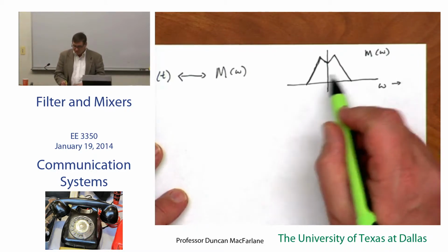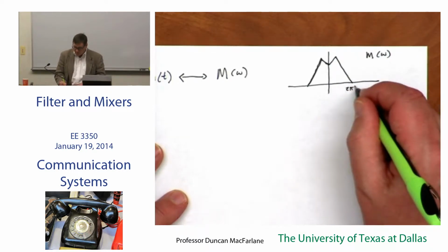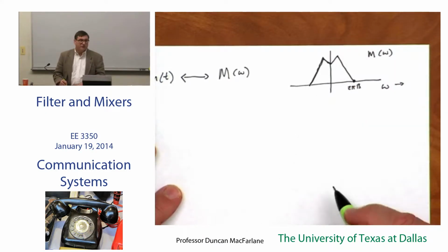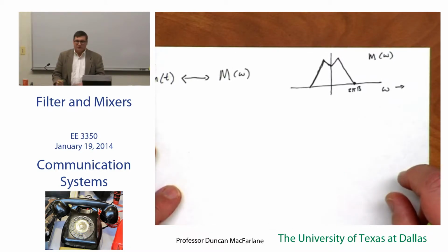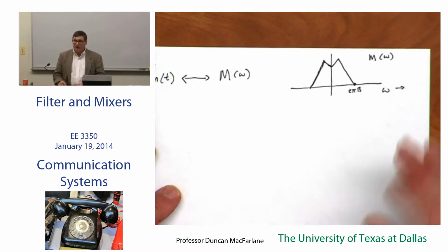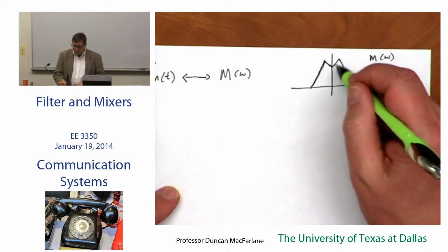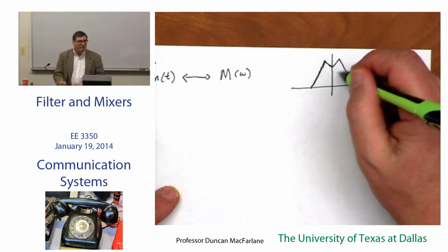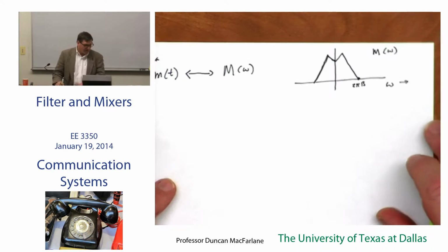The bandwidth of the signal is, let's call that 2 pi B. And so if this were voice, 2 pi B would be 2 pi times 2 kilohertz or 3 kilohertz, depending on where I'm drawing the line. So this little hill is arbitrary. It just says that my speech more or less is at one or more tone of voice. Sometimes it drifts down, sometimes it drifts up. That's all I can really say.